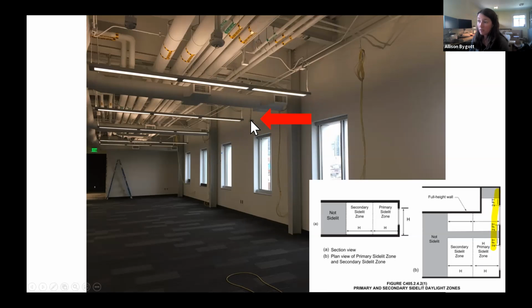This sensor is in an interesting location. It's not too close to the electric light, but it's also kind of up against this wall. I would rather see it spaced in between these 2 rows, but whether or not it's ever going to have a very good view of daylight is really questionable. In this project, the daylight sensor is too close to the light. It's going to read a lot of electric light, and that's also going to be a problem because it's going to have a hard time balancing the daylight that's over here.